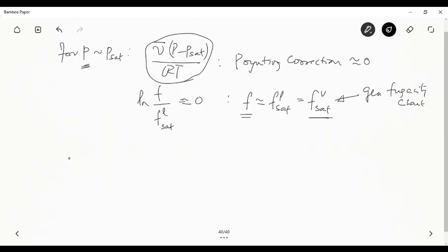In the same fashion, for solids you can start from the triple state, where solid and vapor are in equilibrium, and then integrate. But if the temperature is different from the triple state temperature, then you may not be able to integrate from the triple state, in which case your integration needs to start from the saturation conditions of the phase change of solid to vapor, if it exists at the same condition.